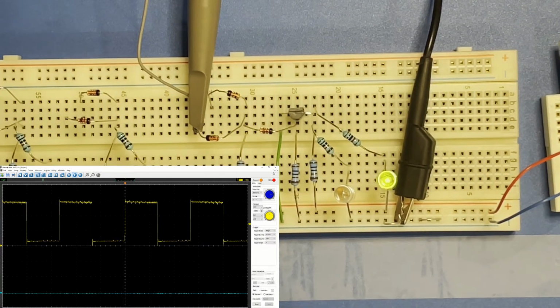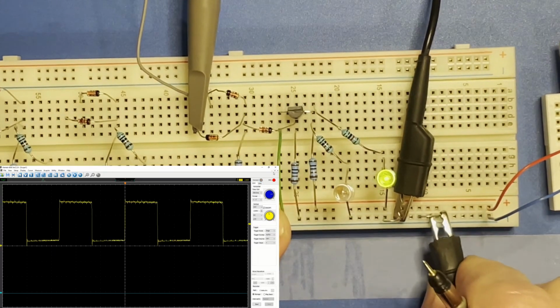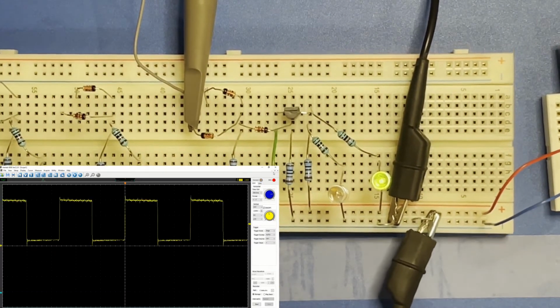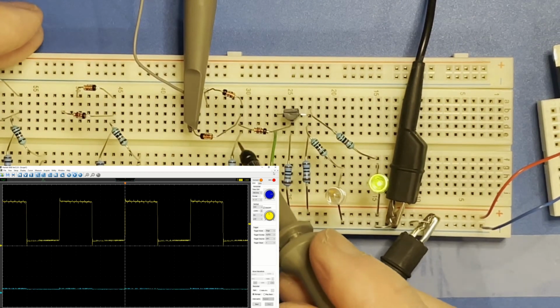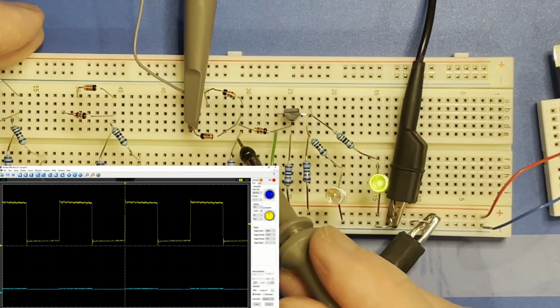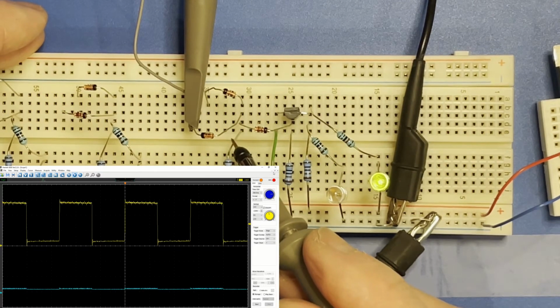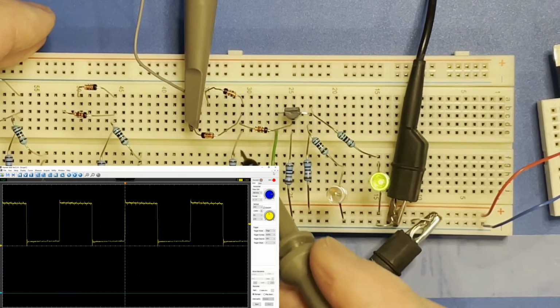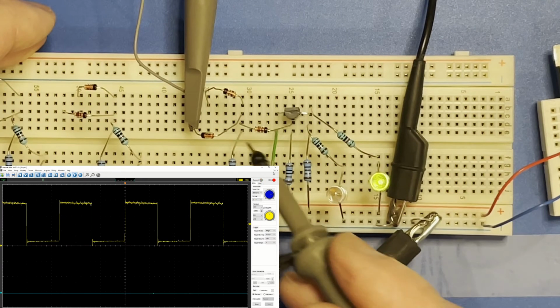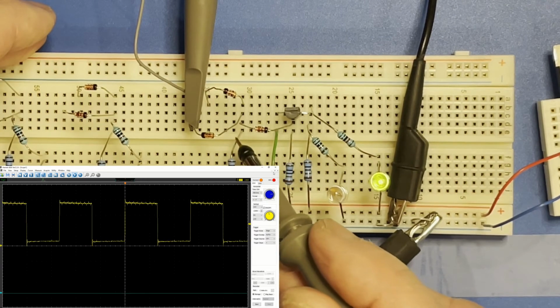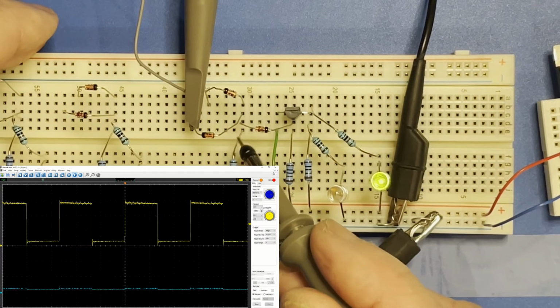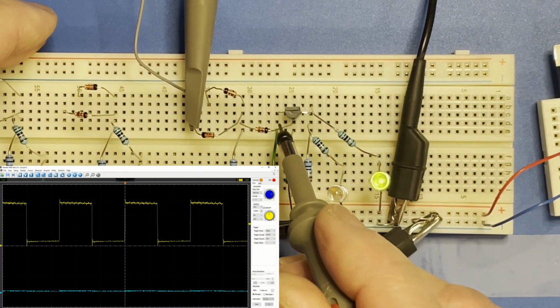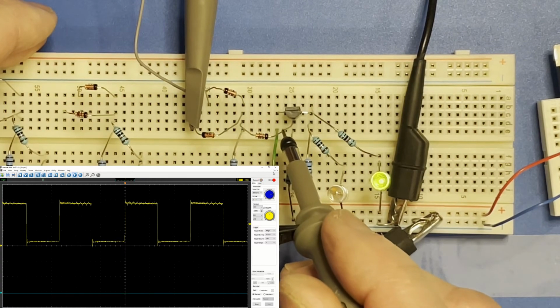For now, grab another probe. These are connected to a little Handtech USB scope box, by the way. Connect that probe to ground and look at the various signals. That's the resistor, which does next to nothing because it's only switching between ground and a fraction of a volt, because the base stops it going above 1.2 volts because of the series diode in the base. So that's still very little on that. There's not enough to get a sensible signal out of that.